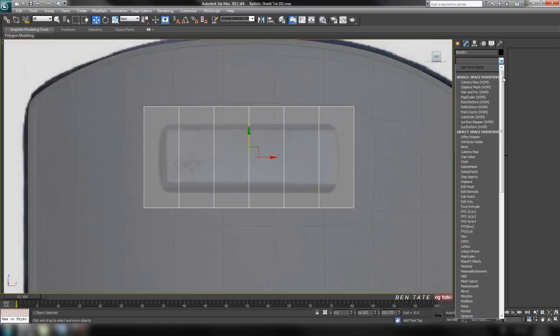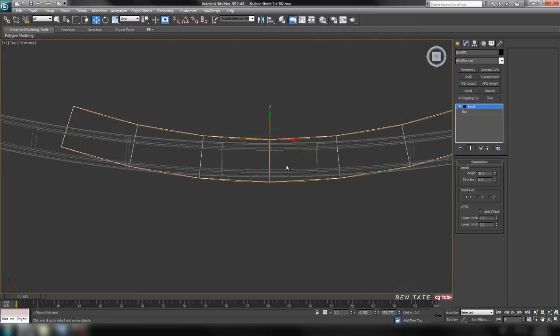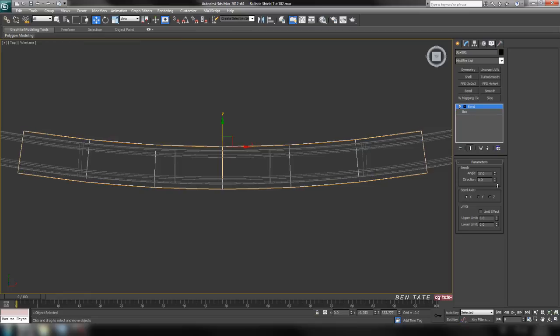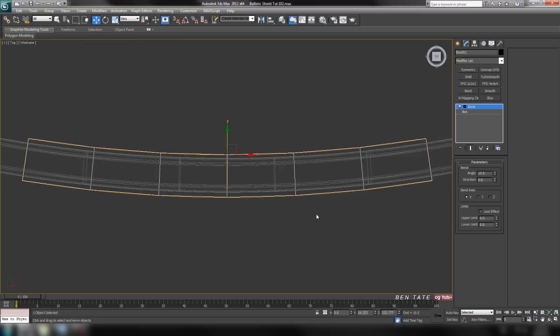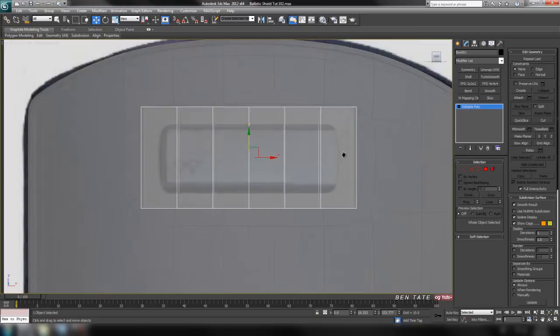and we'll bend it the same way here by adding a bend modifier. All right, let's grab one of those, throw it on, do it again on the x-axis, and let's take up the bend amount here. And in the top view, we'll just try to match the curve of the shield. Right, so it looks like about 17.5 on the x-axis is about what we were looking for. Okay, so let's convert that back to editable poly. Go back into the front view here.